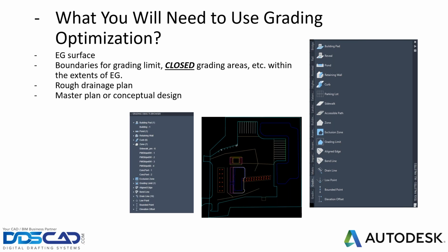If you are familiar with SiteOps, which is a Bentley product, obviously we don't sell that. It's now called OpenRoads SiteOps. It's part of MicroStation, basically, or OpenRoads now. And basically, it's similar to SiteOps, but it's a little bit more granular, and it allows you to have a little more control. In that part, I do kind of like that, where you can actually apply specific types of grading with the grading objects palette.